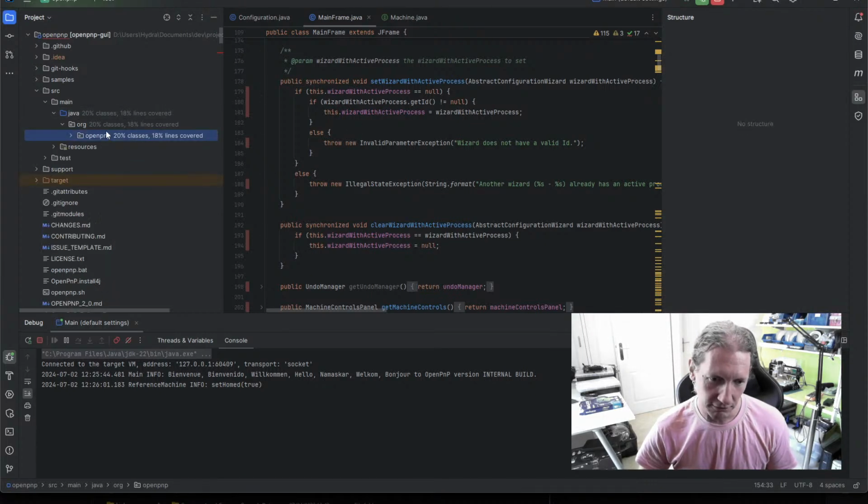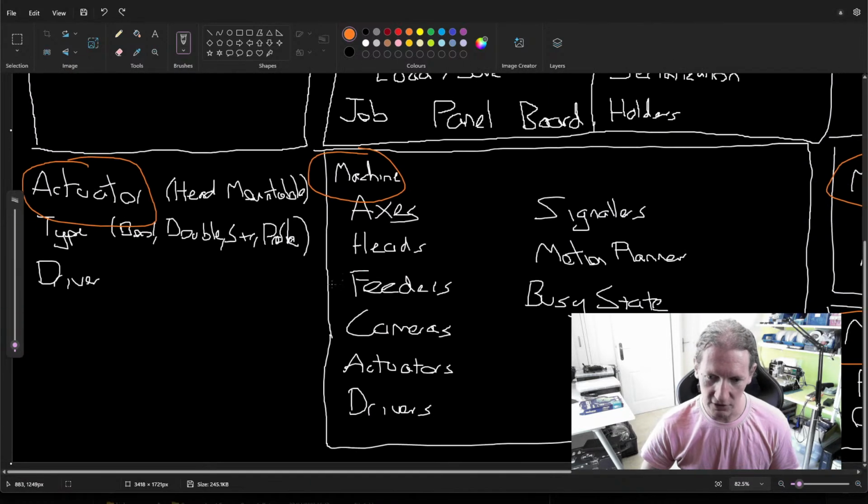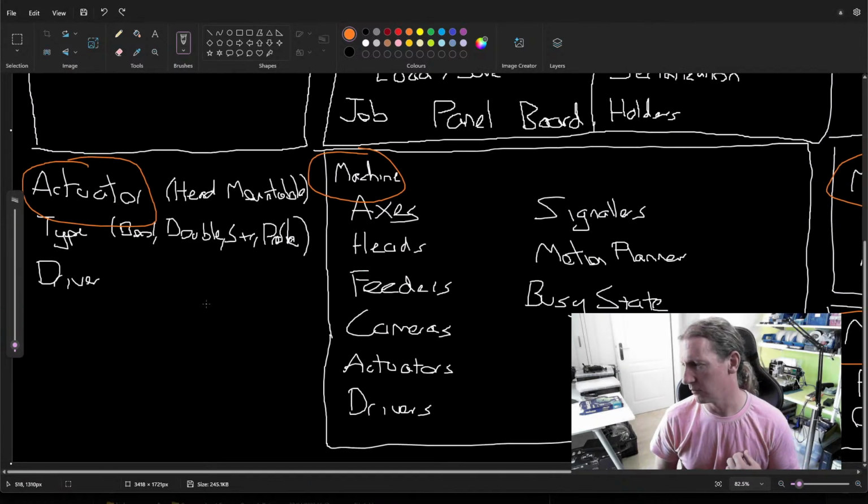And then if you delve deeper into it, you find drivers for interacting with control boards. So the way pick and place machines work is that they generally have a control board which is dealing with stepper motors and vacuum sensors and fans and blowers and pumps and encoders and all this kind of stuff.